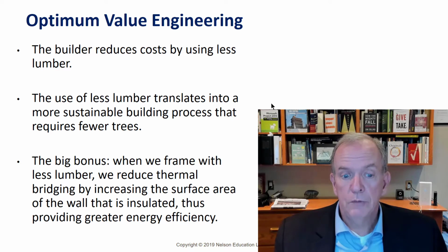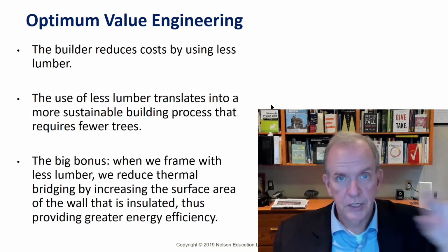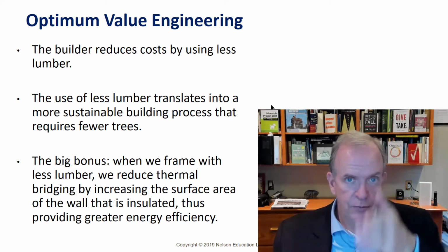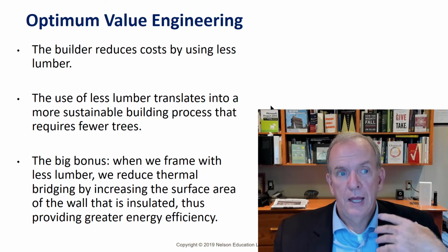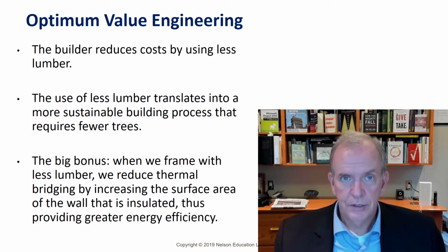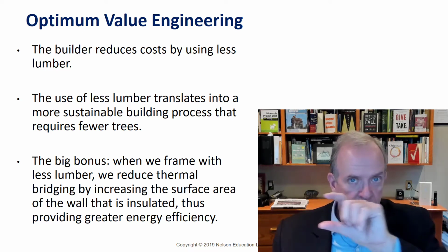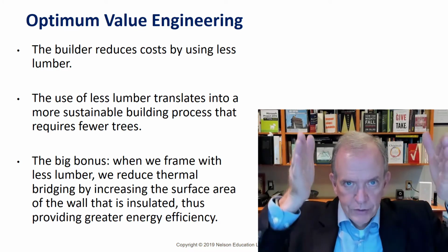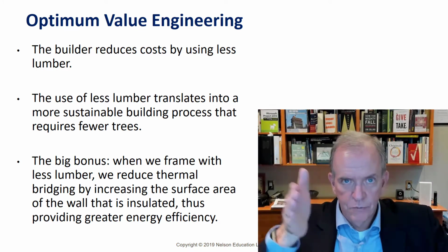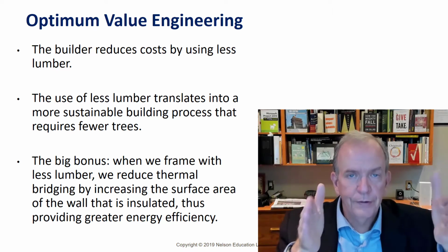Now you could really reduce the lumber by going with a single top plate, go at 19.2 on center, say it was a bungalow, 19.2 on center, and 2-stud corners, use 2x6s, so that could be a real energy efficient boost. But the problem is you've got to make sure that your plates, and whatever is sitting on top, say it's the roof trusses, line up perfectly with the studs.